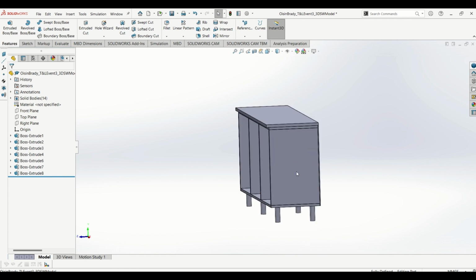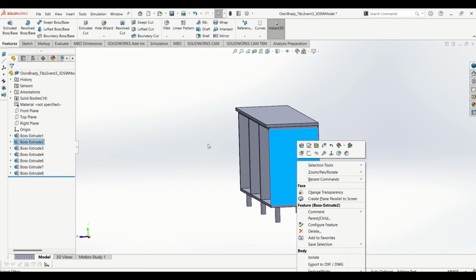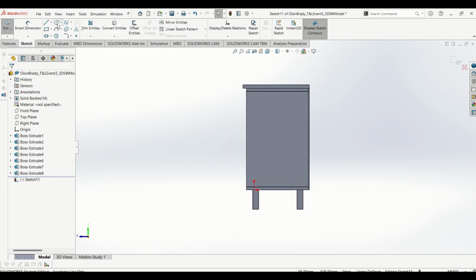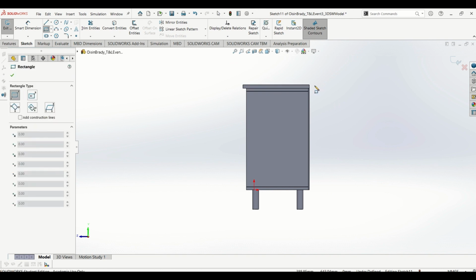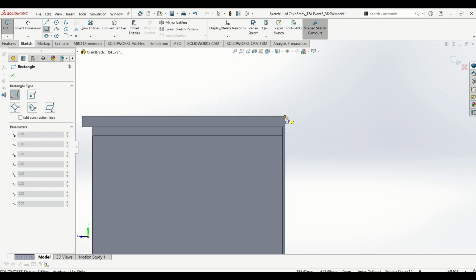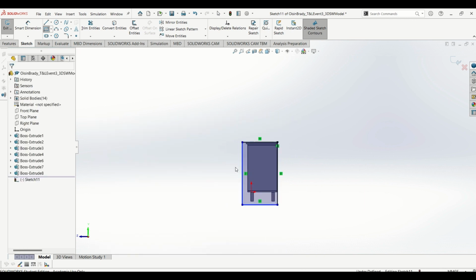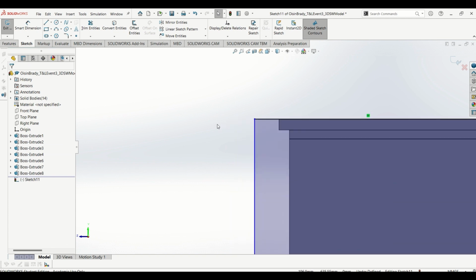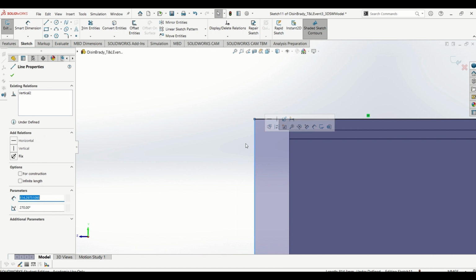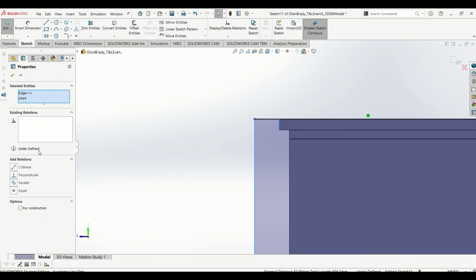So next what we're going to do is right click on our sides and add our 2 blending gables. So this is to hide the feet when looking at the side of the cabinet. So we're going to right click, hit sketch, and use our corner rectangle once again. Go from the corner and we'll come right down. Don't worry about getting it lined up because we're going to use our same method again of left clicking on the line, holding control, and left clicking on the edge we want to make it collinear with. So this will make them in line again.